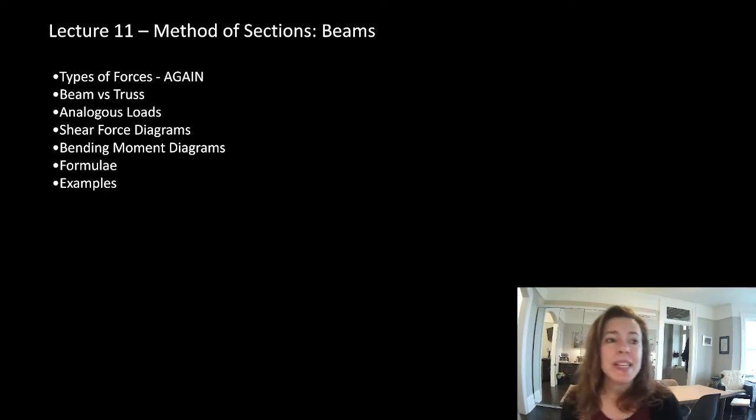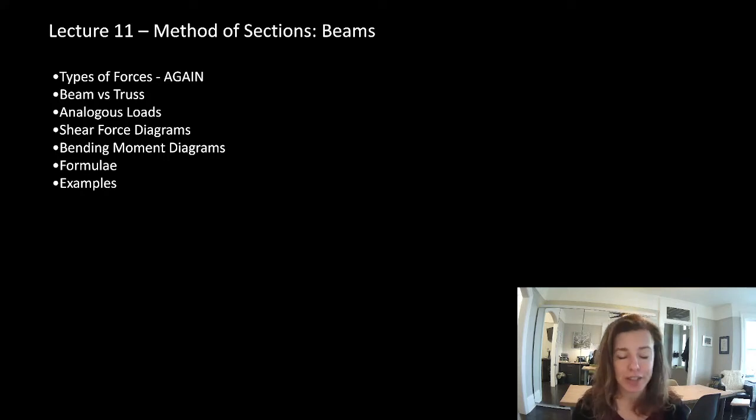Okay, so this week we're going to keep talking about this concept of method of sections. And I really love this lecture because it's where all the ideas we've talked about so far this term come together. At the end of this, we will be able to figure out what all of the internal loads are on our elements. And remember, the whole point of everything we're doing is making sure that the reduced capacity is greater than the factored load. At the end of this lecture, we will be able to determine the factored loads on things.